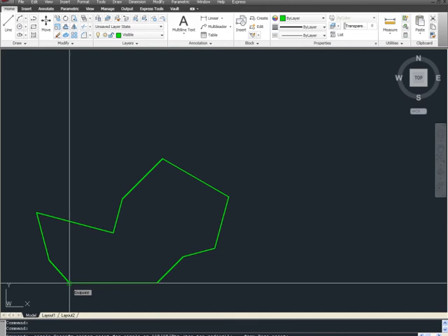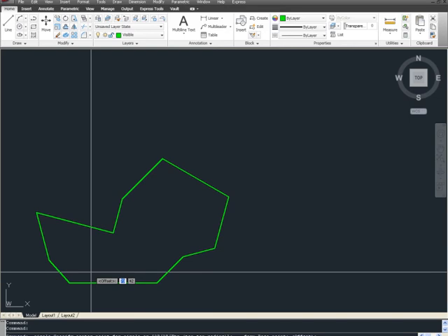And I'm using that point because all of the dimensions for the location of the slot are relative to either line A, B, or this particular point. So I'm going to snap from that point, and at the keyboard I'm going to type at 21, 34 and press the Enter key.